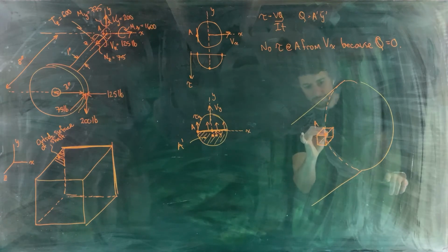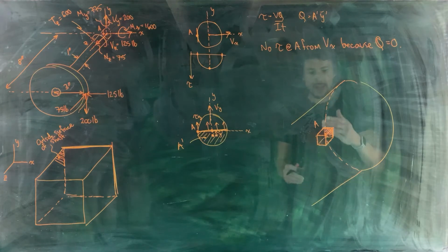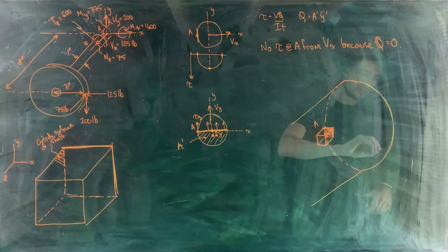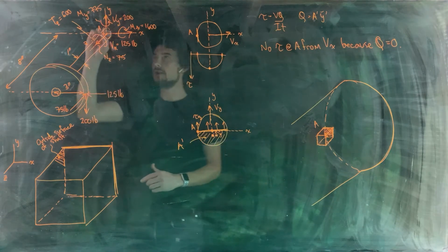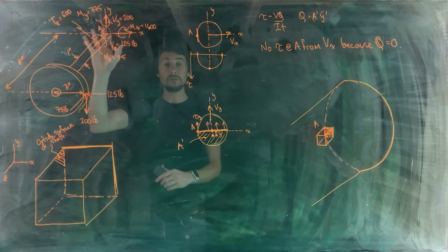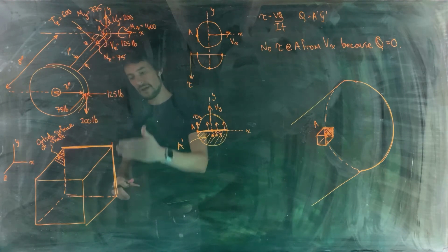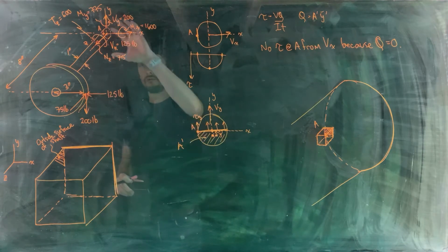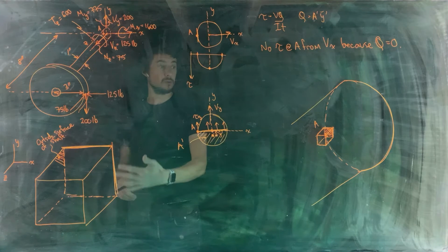Okay, so the face that I've shaded or outlined, which is the back face here, that back face of the element of material is sitting right in the section plane that we've cut to expose point A. So that's important because all of these internal forces and moments that we've drawn act on this plane of the volumetric element that's present at A. So all of the stresses resulting from these internal forces act on that face of the element. So that's where we're going to place them.